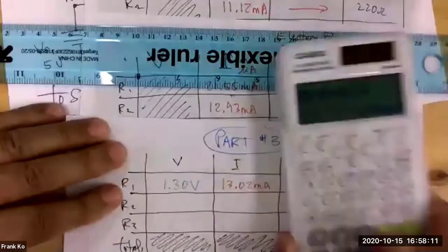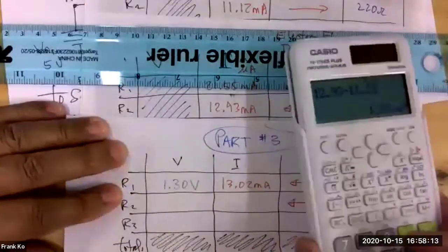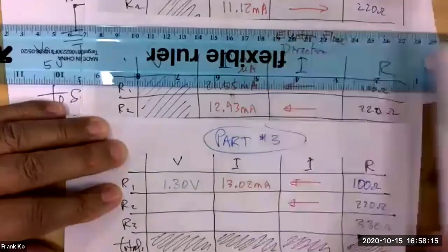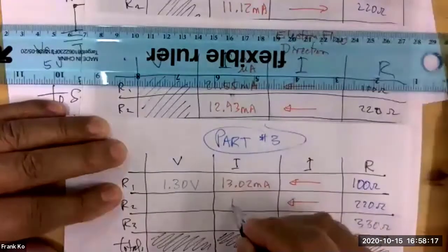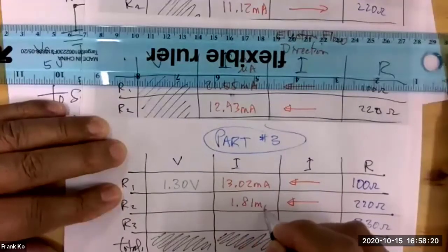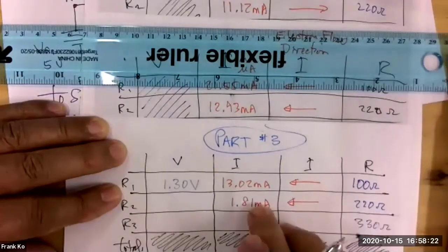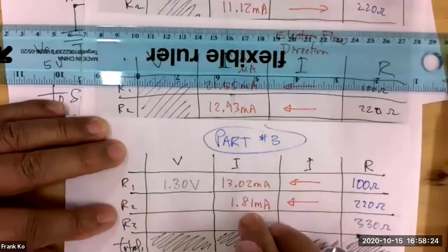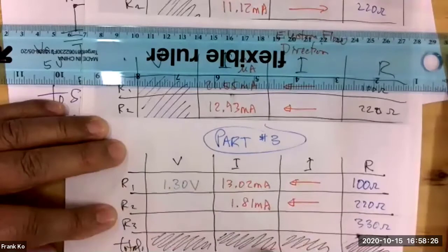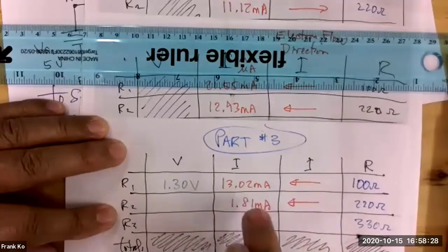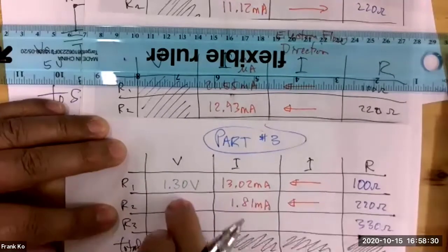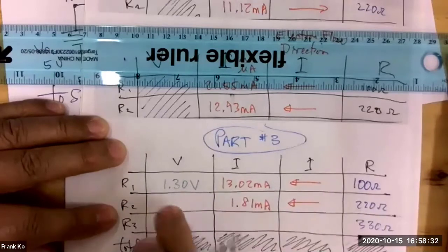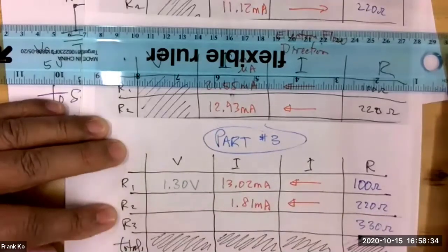Okay, all right, you were scaring me. I also have it written down. 1.81 milliamps. Cool. Is everybody happy with that value and understand why? And now on our final sheet, our part 3 sheet, do I have enough information with a current and ohms to calculate a final voltage across R2? Yes. Let's go ahead and do that.